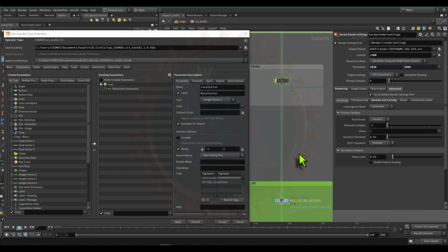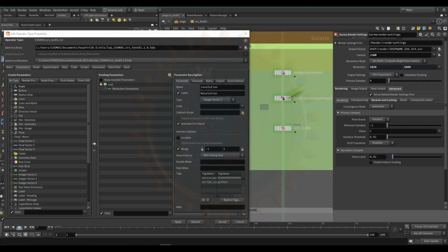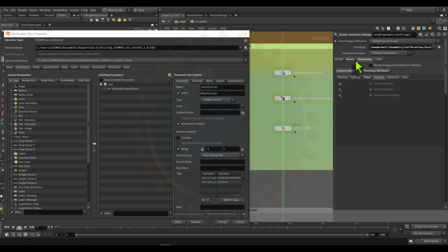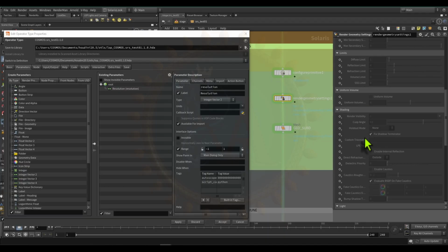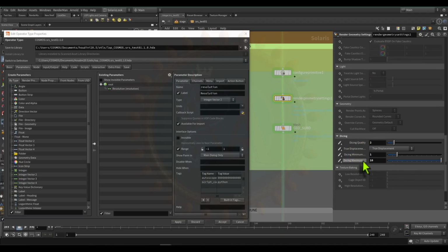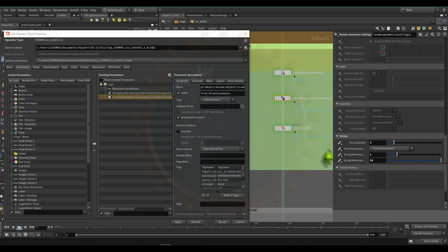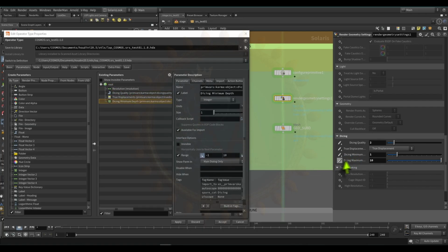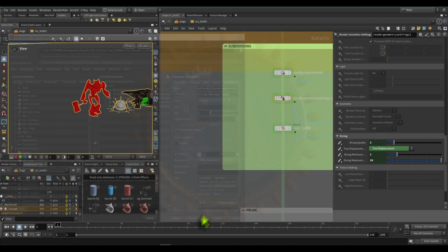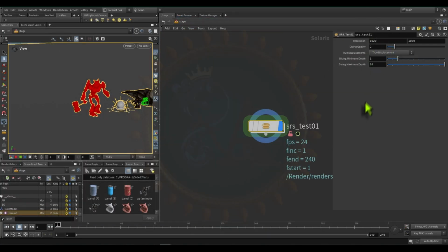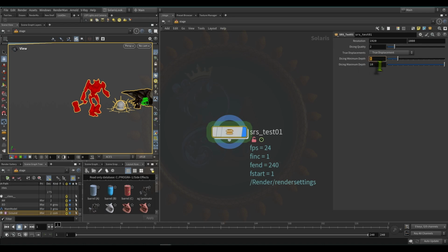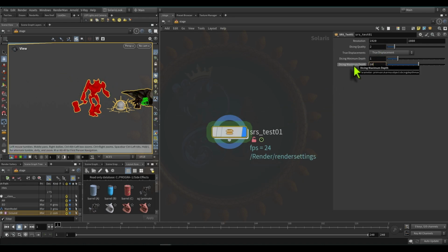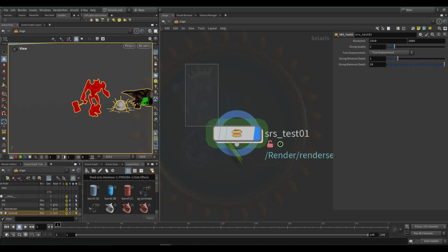So I want to control these settings. For example, I'm using a camera, right? There is a dicing part I want to control, so I can drag all of them. How many subdivisions you require. Now accept. Okay, you don't need to worry. Come back, and when you select, you'll see all of them. So directly I can control how many subdivisions I want. If I want 25, some jagged edges will come, so minimum 10 is good. So like that, this is done.